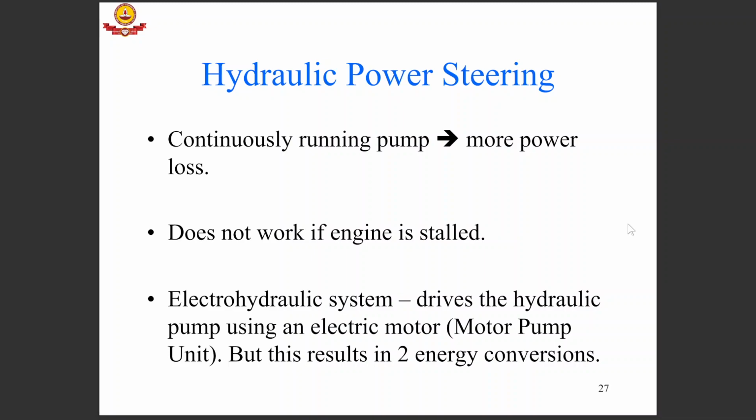This kind of system will not work if there is any kind of engine failure. So an electrohydraulic system is one where an electric motor drives the hydraulic pump, but this results in two energy conversions, first from electrical to mechanical using the motor, and then mechanical to hydraulic.